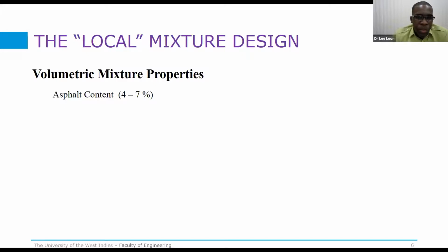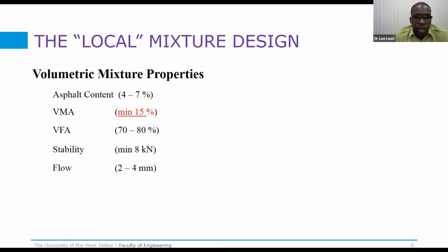Our mixture specification usually includes asphalt content, the VMA, the VFA, stability, flow, air voids, and sometimes density. Now, sometimes one of these properties is not being met in terms of the specification it is being measured against, but does that mean that the roadway or the pavement structure will not perform within its given life?